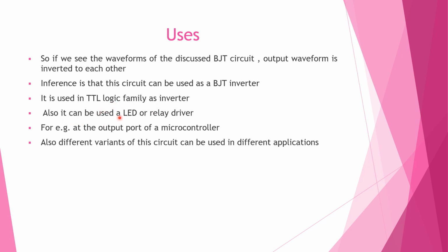Another use is that it can be used as a relay or LED driver. That is, at the collector emitter loop, you can connect an LED and then give a voltage at the base terminal, and with a small current we can drive an LED which takes some 10 or 50 times greater current than the base terminal current.